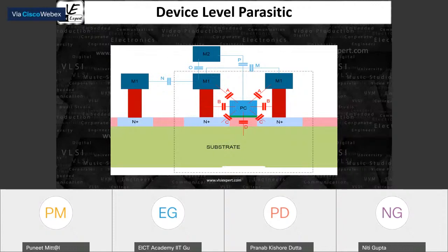So just to give an idea, if you are talking about parasitic extraction, it can also extract the device level parasitics. Last time, the metal 1, metal 2, metal 3 that I discussed, that is the metal layer point of view. The cell level extraction we usually talk about is when the cell is already there, and at that time if you want to extract, you are talking about metal 1, metal 2, metal 3 type of extraction, the parasitics, especially the resistance and capacitance.